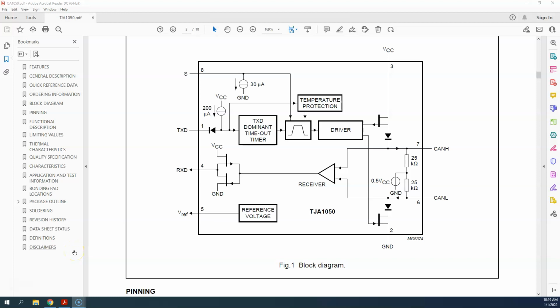Hey, in this fifth installment of Advanced J1939 we're going to take a look at the receive component of the CAN transceiver. The transmit component, as we talked about last time, is some device like a microcontroller outside of the CAN transceiver that will send a signal when we want to transmit. So we're going to transmit either a logic 1 or a logic 0, driving the CAN bus so that the difference in voltage is approximately 2 volts or 0 volts. Those correspond to the dominant and recessive bit.